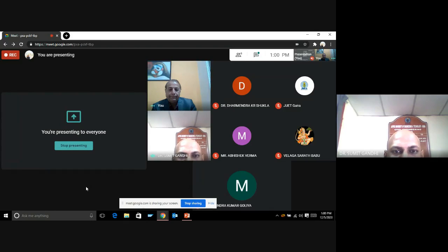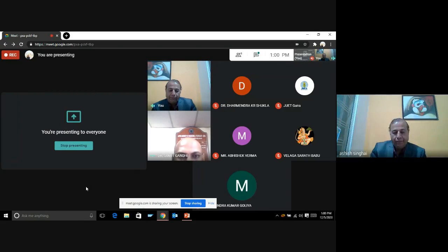Okay. Sir, then another question is from Mrs. Shikha Pandey. In pervious concrete, how can we stop clogging? Yeah, this is one challenge that is often faced in pervious concrete applications. So we need to have continuous cleaning of the top of these pavements which are constructed using pervious concrete. So the top area has to be cleaned continuously.